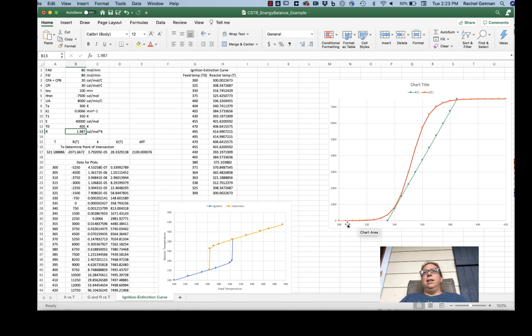Basically, on the CSTR curve there are regions where we can be operating at multiple steady states. The one that the CSTR will operate at is the one that's closest to where we initially were. The important issue here is where the reaction will light off, and also where it will start to die off, meaning the feed temperatures that will do that.